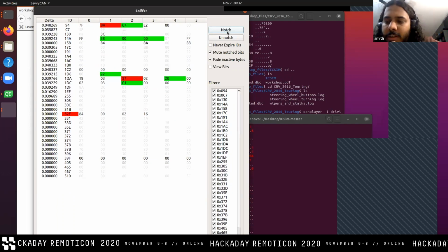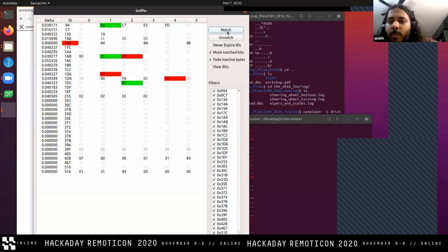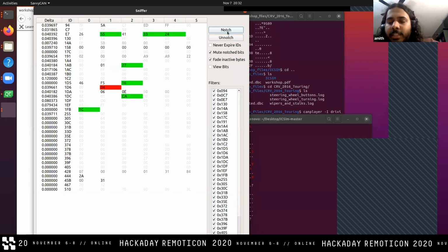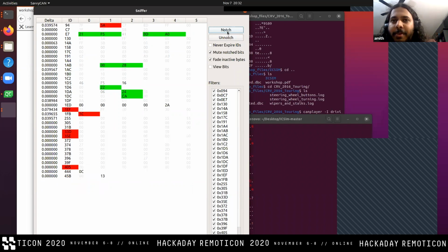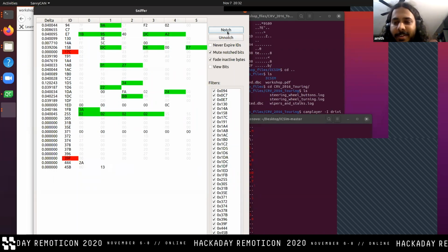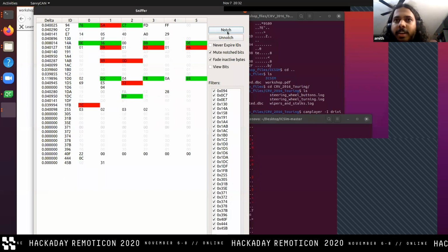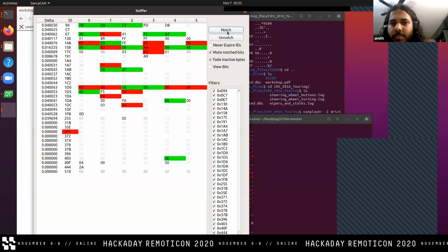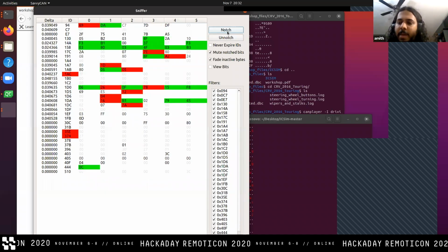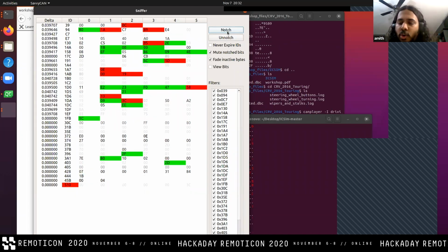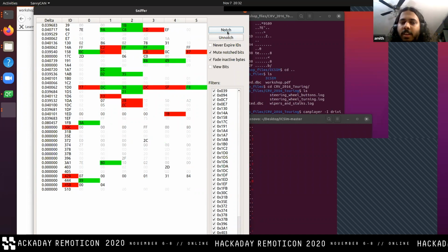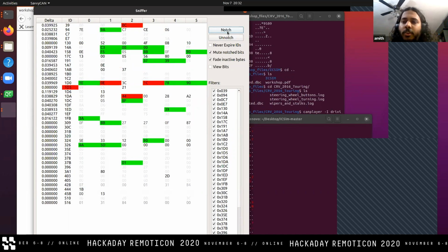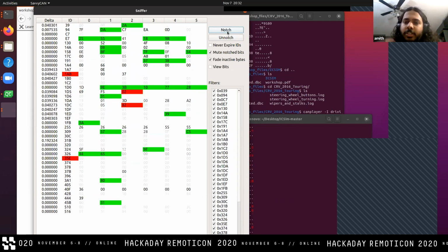Piotric asks, are there any downsides of replaying thousands of CAN commands into an actual car? You should never replay stuff into a moving car. Whenever I've done it, I've always done it in park, and I have my wheels blocked off so the car can't go anywhere. And newer vehicles have an electronic transmission, so you have a danger of putting it into gear using a command.